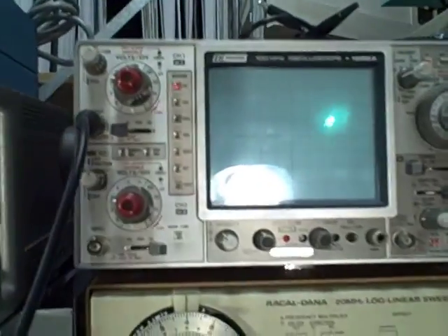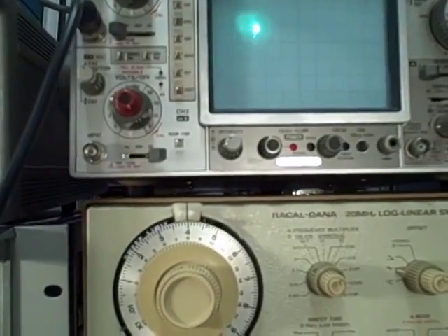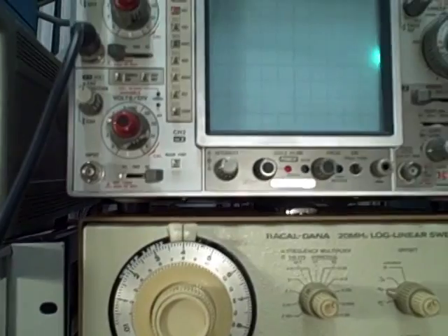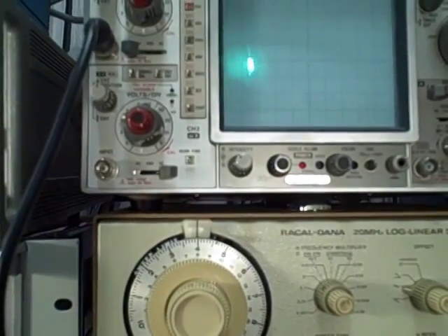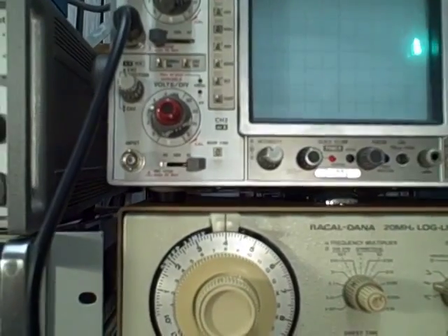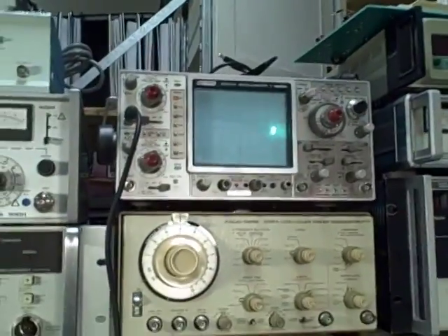But according to my oscilloscope, we're putting out about 1 hertz. So we're getting about 2 divisions per cycle, and we are on the 0.5 seconds per division. So that would be 1 second in 2 divisions, and that would be 1 cycle. So we're at 1 hertz right now, 1 cycle per second.